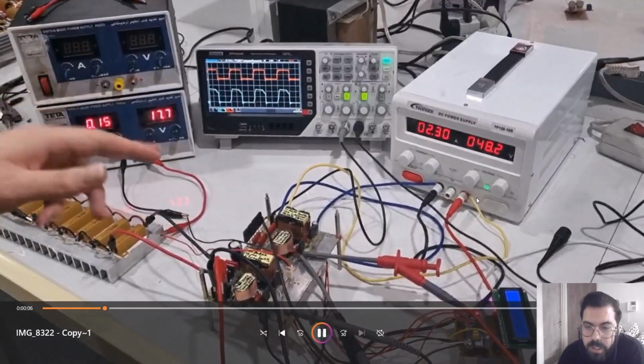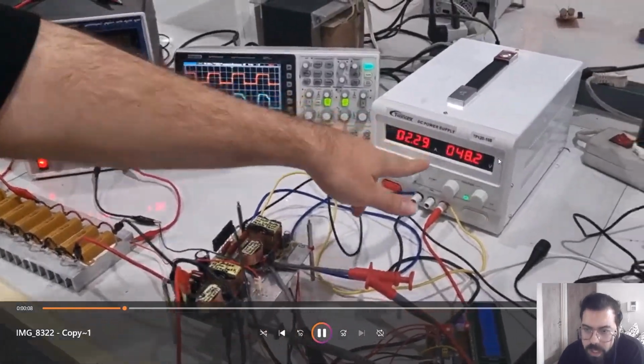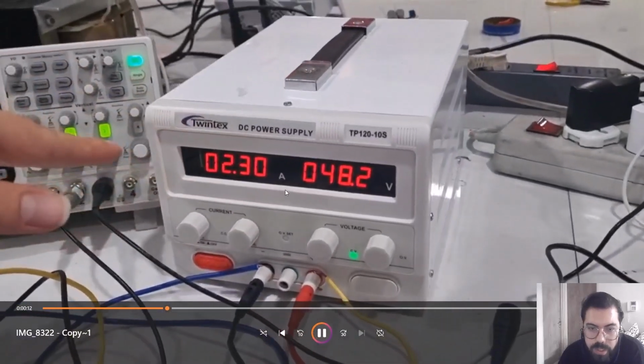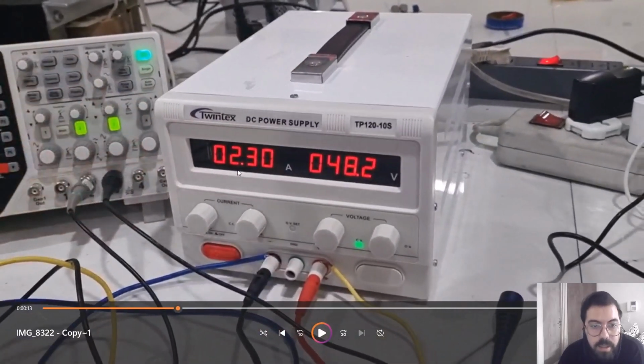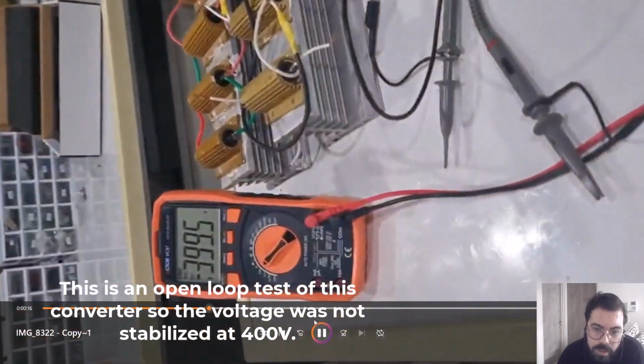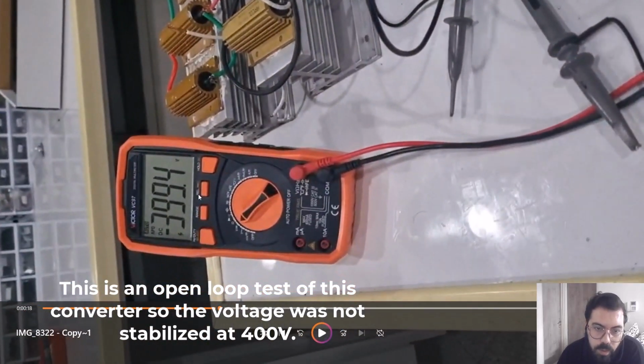Now as you can see, I gave 48.2 volts to those input ports, and the current of these input ports is about 2.3 amps, and if you multiply them, you can understand that this power supply is giving 100 watts to the converter. So now this is the output voltage of this converter, which is about 400 volts,